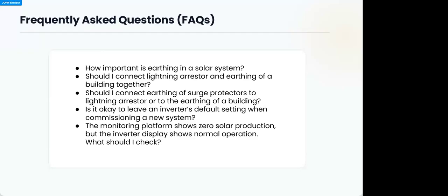Thank you. Earthing is very important to life and property, because it's not only the system installed that you want to protect, but also the people, anybody that may come in contact with it. Because if there's a fault on the system and it is not earthed, and the body of the equipment happens to have contact with live, there is nothing to drag it to the ground where you stand as a human being.